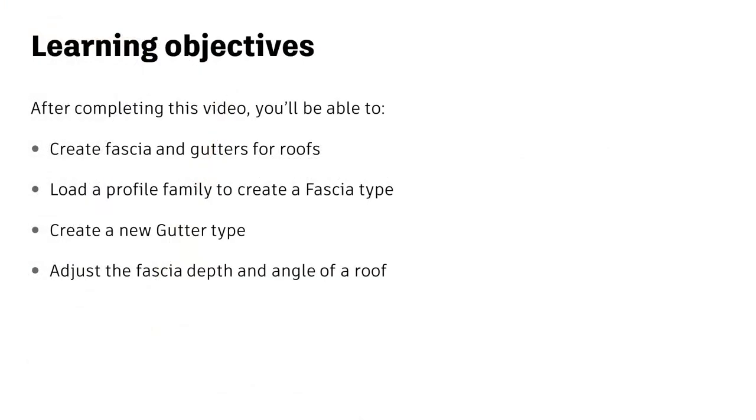In this video, we'll see how to model both fascias and gutters along the edge of a roof. We'll show how to load a profile family and how to create a new fascia type using that profile. And we'll also see how to create a new gutter type by duplicating an existing gutter, and how to adjust the fascia depth and angle properties of a roof.